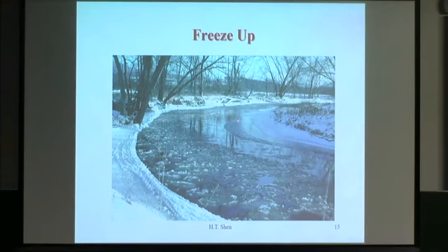This is the border ice. Well, this is in a band, and typically it's deeper here, shallower here, slower velocity, higher velocity. So here you form smooth border ice, okay? And here you have ice pans, pancake ice start to develop, and you can see them. And then the border ice on this side, I call it dynamic growth of the border ice. It's due to the interaction of the surface ice flows with the bank.